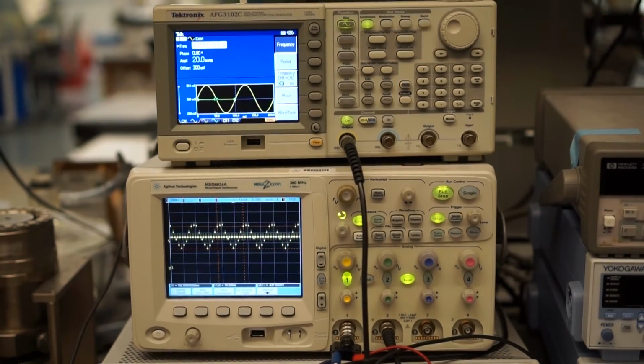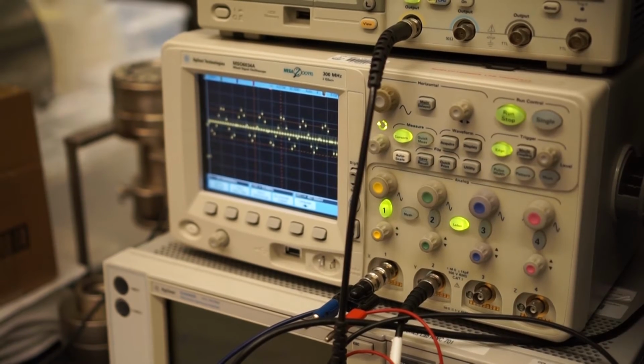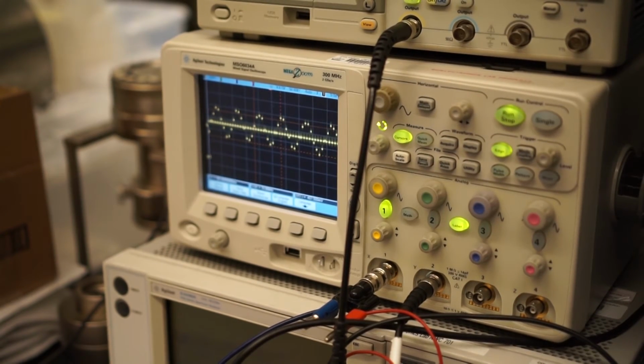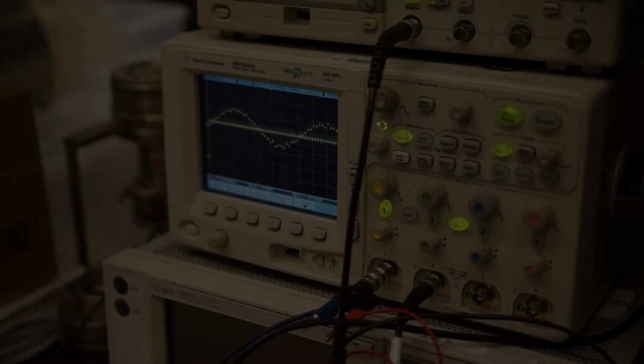Now you are looking at the output waveform of the current integrator-based transimpedance amplifier, with a 20 picoamp amplitude, 10 Hz sine wave current as its input. The output voltage is about 200 millivolts in amplitude, which means the current integrator with this configuration has a transimpedance gain of 10 gigaohms.